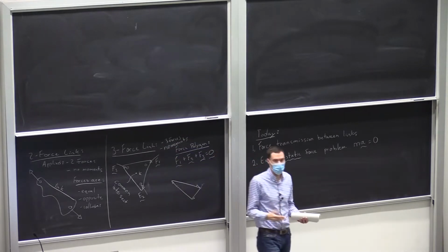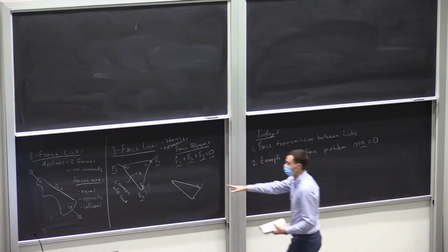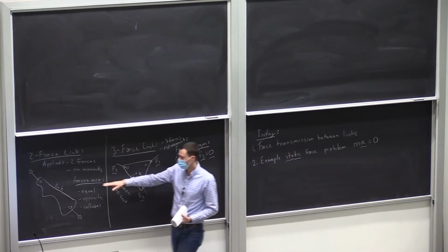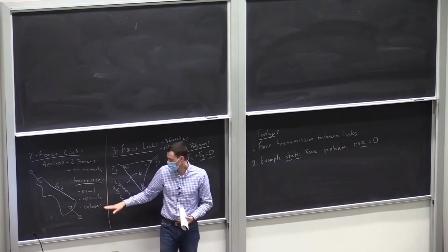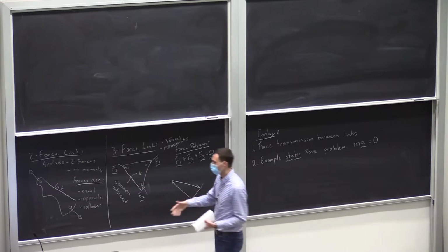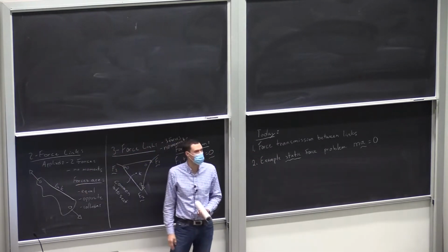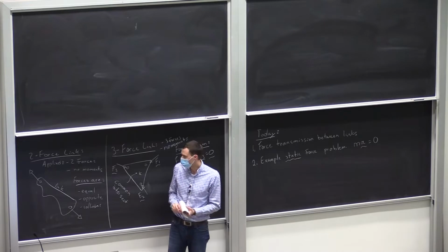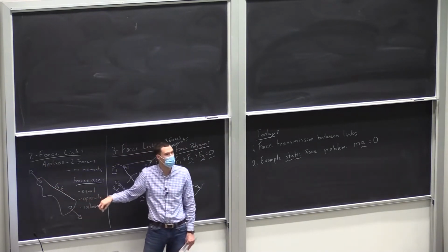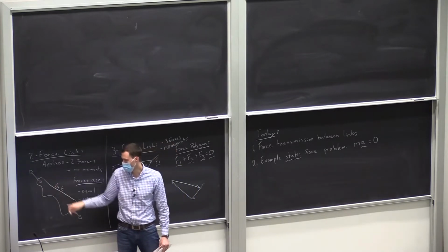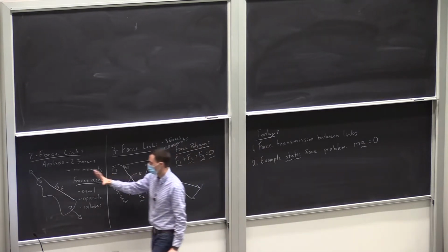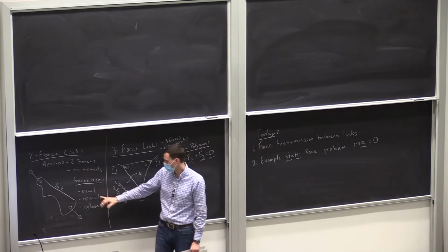OK, and if that qualifies, you can take the shortcut. These two-force and three-force links, we already solved them generically, and we had these conclusions. For two-force links, the forces are equal, opposite, and collinear. So on an analysis problem, you should have an eye out for every two-force link, and you'll get really good at finding them. Usually if the links are connected by turning pairs to other links, that's a good clue. Turning pairs can't transmit a torque through them. And if they only have two turning pair connections, already, you're done. You've solved that link. Equal, opposite, and collinear.